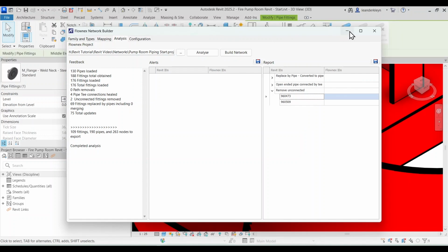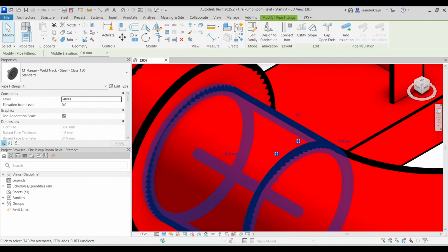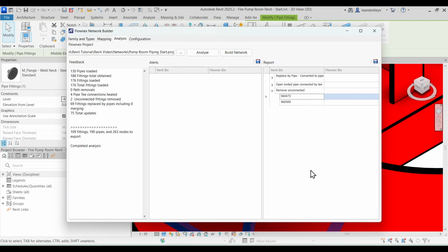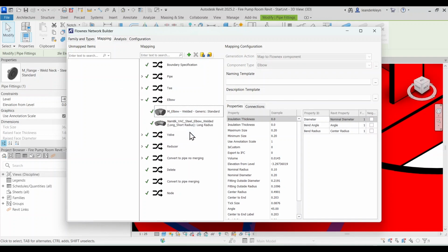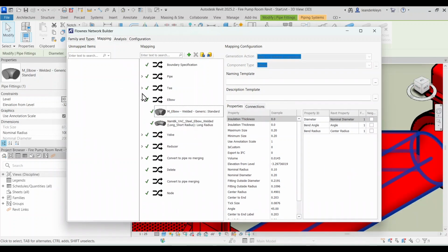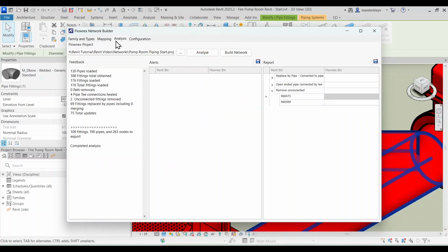This report allows you to review the planned actions and focus on specific areas that the Network Builder will alter or repair when the export process is executed. It will also issue alerts or error messages for Revit issues that it cannot repair automatically and guide you to the problem areas where the issues can be fixed manually.